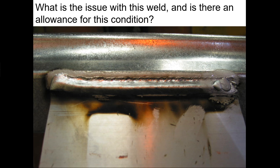I have a suspicion that there was a dirty nozzle involved again, because we've ended up with a lot of black starting to form, and that black represents the aluminum that's flying around inside the puddle, around the puddle, the argon that's flying around. It gets trapped in it, and then it gets outside the argon shield, hits the air, and turns black. Just the same way we form aluminum oxide, and it looks black.